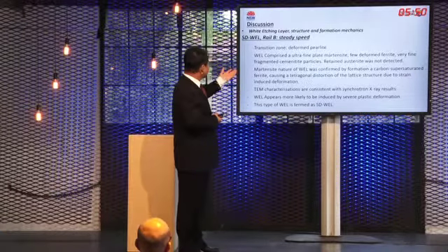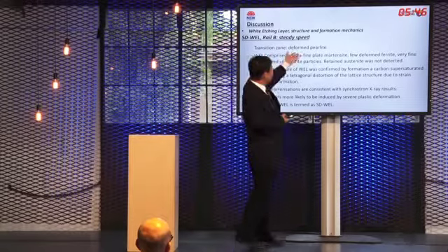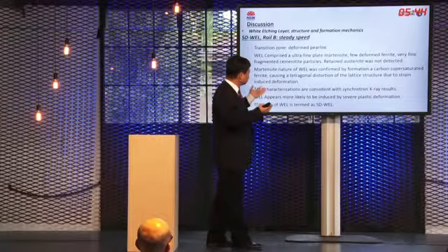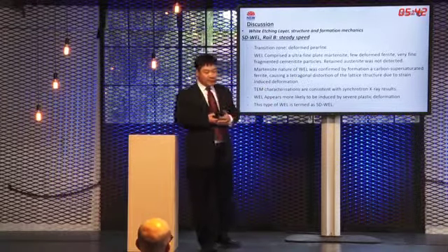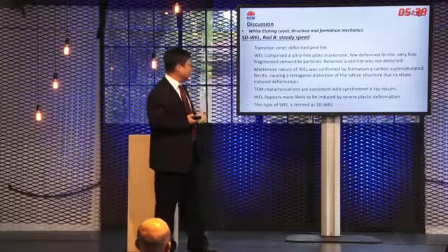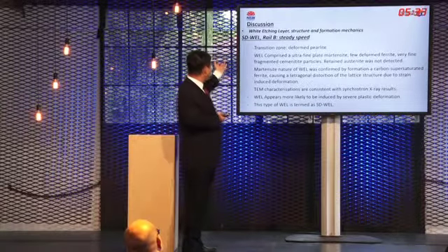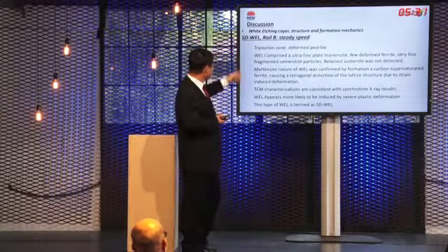For region B, stable traffic, you have deformed pearlite, no austenite. The formation of martensite is caused by carbon supersaturation. It's caused by the plastic deformation. So we call it the severe plastic deformation white etching layer.